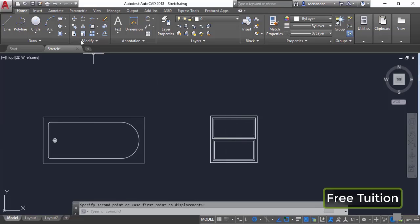So I'll once again select the stretch tool, and now in this case let's assume that we want to increase the height of this panel here, and we want to keep this panel unchanged. So for that we need to make this stretching window in a specific way, just like this. Now in this case we have these 6 line segments which are crossing this crossing window, and they are partially inside and partially outside. Rest of the geometry will remain completely unchanged.